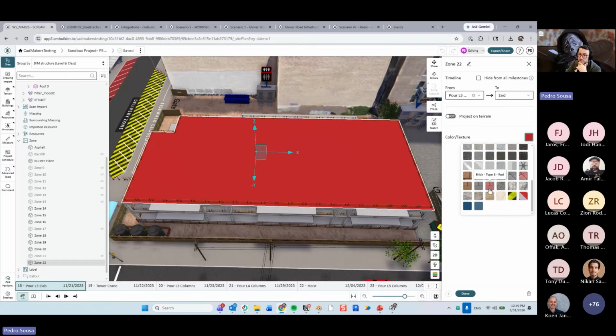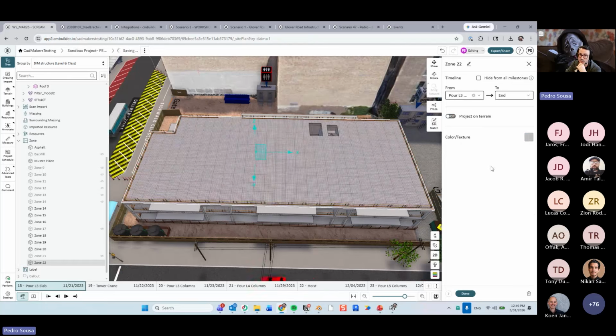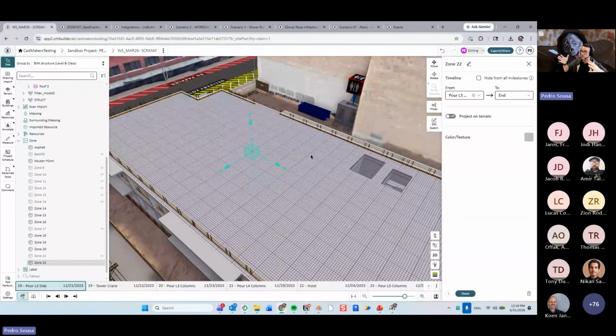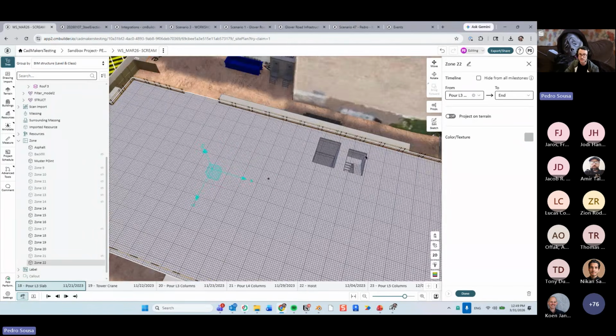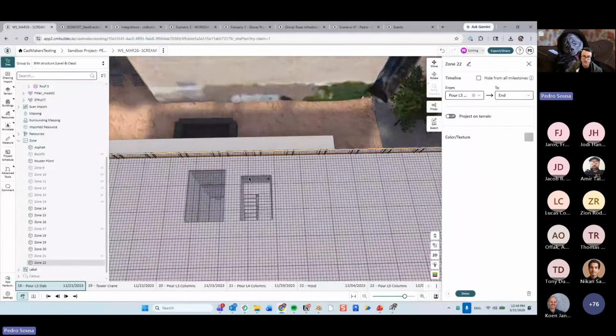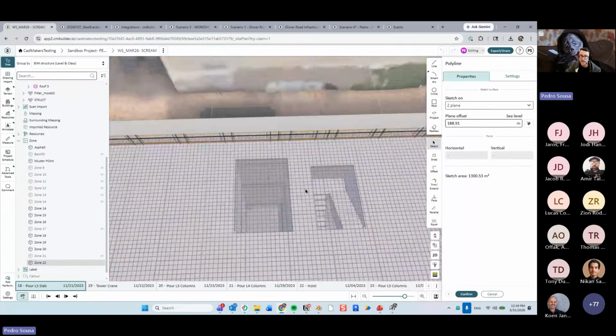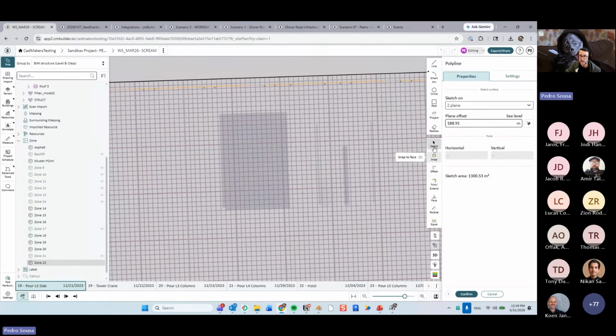And now we have this new rebar material over here that basically, instead of you adding resources and adjusting the resources to fit this geometry, you can use the rebar zone to quickly create those. And now for these areas over here where you want to create a remove function, you can go in and then add some rectangles to remove the zone in this area.